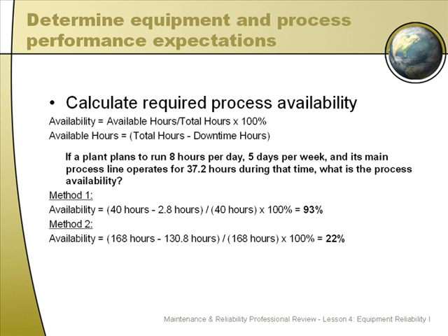Well, why would we use these two numbers? The first one is really useful for measuring the availability inside of the framework of what your production intentions are. So it tells you how well you're using the time you plan to use. The second availability figure is useful in telling you what the maximum output of your operation should be. In other words, in this example, this same plant if its rated capacity will allow it, could generate almost 5 times as much productivity as it does under the current circumstances.